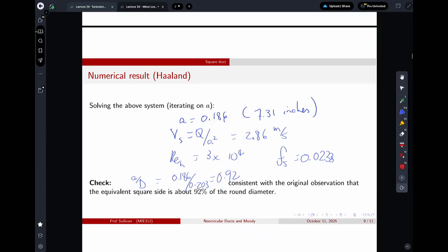Again, it's setting up the equations that's the hard part. Using the Haaland equation, I skipped a lot of work. If I were to do it by hand, I'd probably take more iterations than in a normal problem. Normal problems, you saw that most of the type 2, type 3 problems that we did, we could do in 2 to 3 iterations.